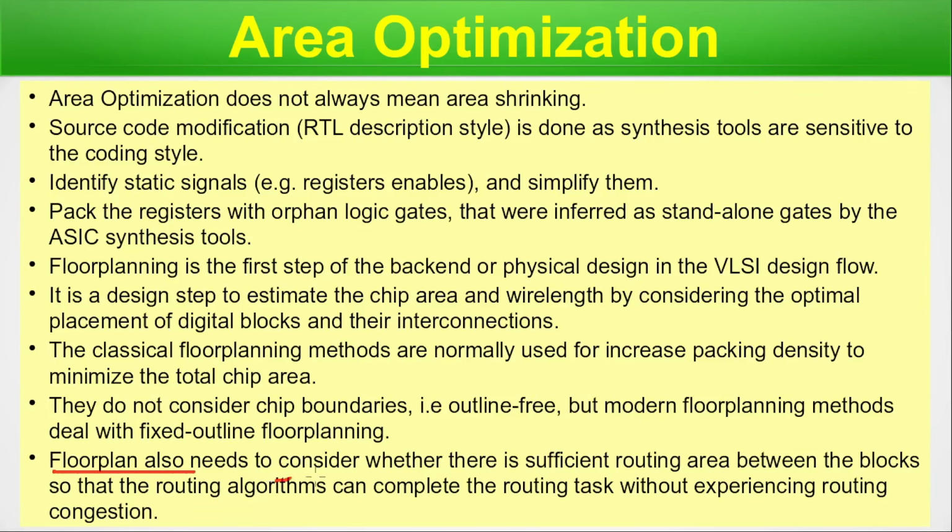Floor plan also needs to consider whether there is sufficient routing area between the blocks so that the routing algorithms can complete routing tasks without experiencing congestion. We talked about the congestion, right? Dealing with the congestion is right at the floor planning stage, and this is one thing that the area optimization needs, because we need to manage everything.